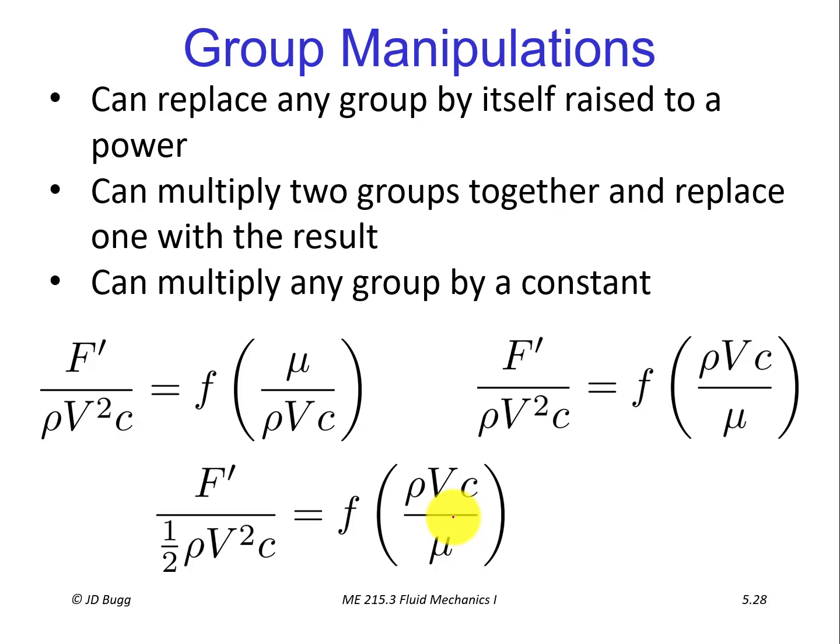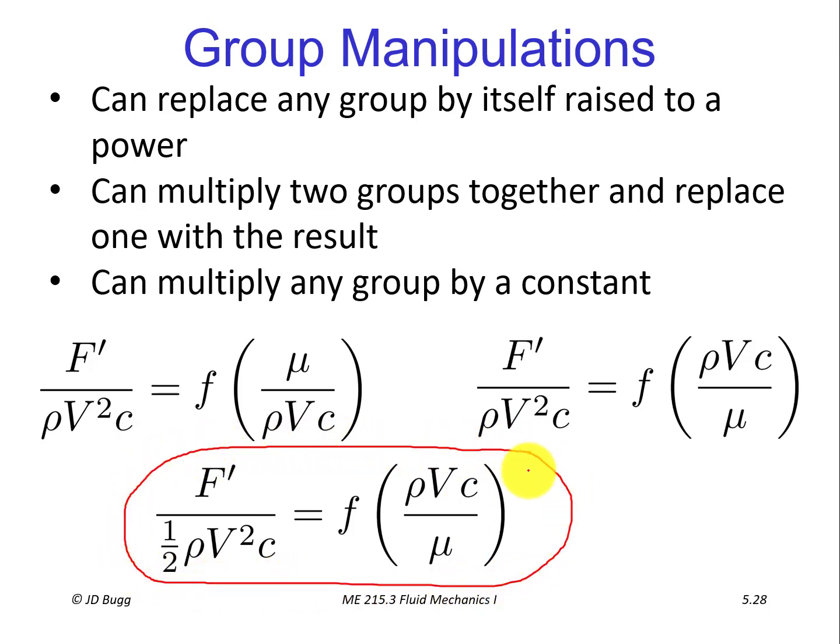aerodynamics. So this is our first illustration of how we would use the Buckingham PI Theorem to guide us towards the appropriate dimensionless groups to study a problem like this. And it's brought us to two very, very conventional quantities in aerodynamics, a drag coefficient on the left-hand side and a Reynolds number on the right-hand side.